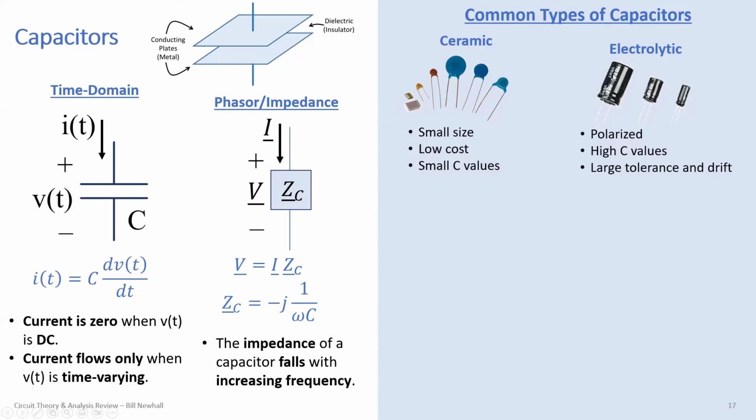Notice in lab, when you're working with this capacitor, that these are polarized. You'll usually see a minus sign next to one of the leads. Sometimes I've seen a plus sign next to one of the leads, but pay attention to the polarity, because if you put these in with the wrong polarity, after a while, you can degrade the capacitor. It'll stop working. And in lab, when you're building up your motor driver circuit, pay attention to the polarity of the capacitor and the noted polarity on the schematic and the circuit board.